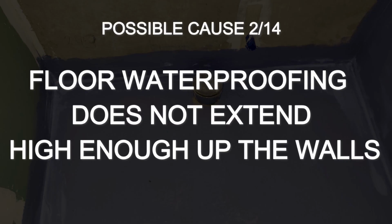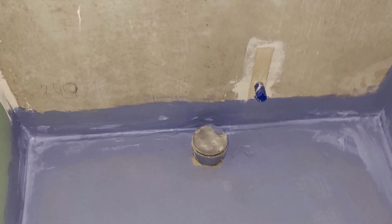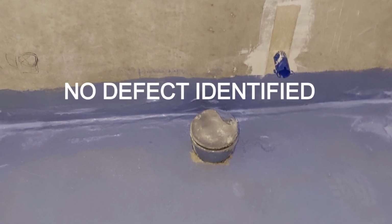The second version, the floor waterproofing might not have been extended high enough up the walls. In that case, water accumulated on the floor could seep into the wall structures, but construction photos showed that the waterproofing was extended sufficiently high up the walls. We did not identify this defect.